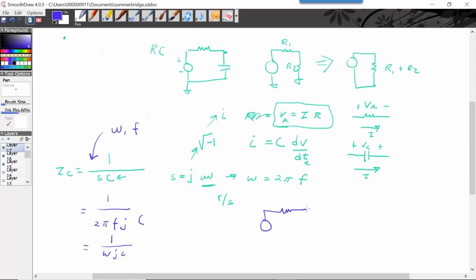And that allows us to use this kind of functionality, where if I have a resistance and my capacitance, and that's ZC and that's ZR, I can transform this circuit into a combined impedance, all right? And now what I have is a complex number because this would be real and this would be purely imaginary, all right?